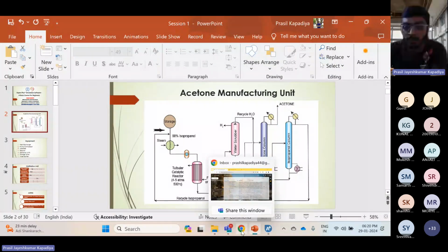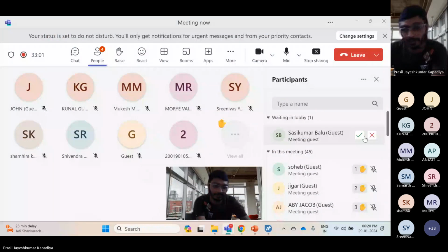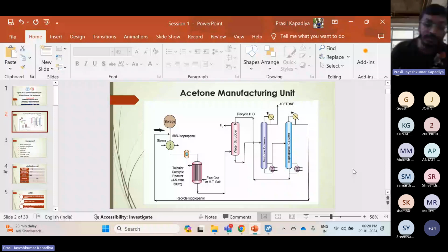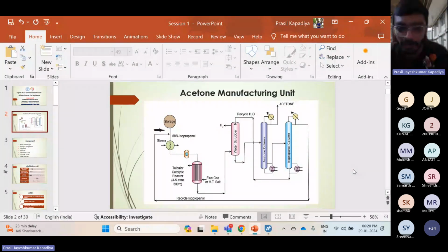Another reason we can also think of is the compressor. What do we generally feed in a compressor? Is it gas or is it liquid? Gas, always gas, without a trace of liquid. So we need to increase our feed temperature, because what a compressor does is it increases pressure and it reduces temperature to some extent. So what if during our process, vapor is converted into liquid? That is not desirable for our compressor. So that is also one of the reasons why we first go for the heat exchanger and then we go for the compressor. Okay, is this clear to everyone?